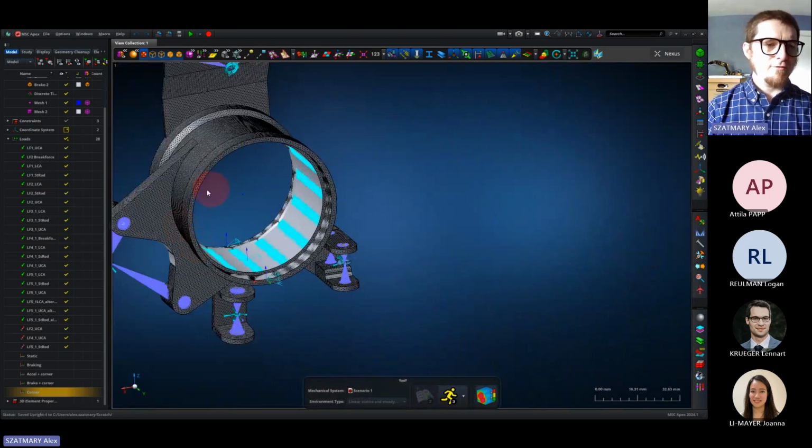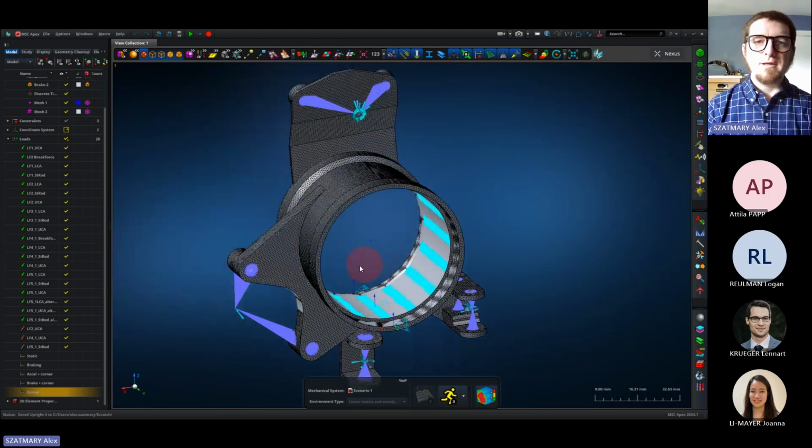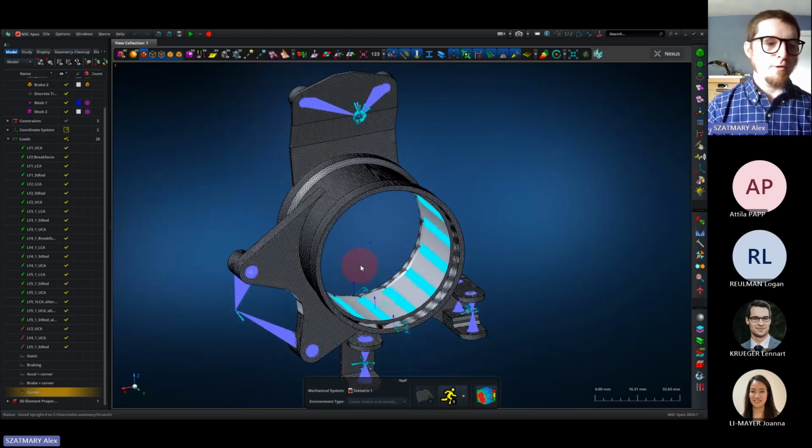There are some parts here for which the mesh really is honestly still a little bit too coarse, but this is much better than what I showed you before. You can see that I have many more loads here and 5 distinct load combinations that combine those different loads. So different cases for static loading, braking, accelerating or braking while cornering, and then simply doing cornering right in the middle of that operation.